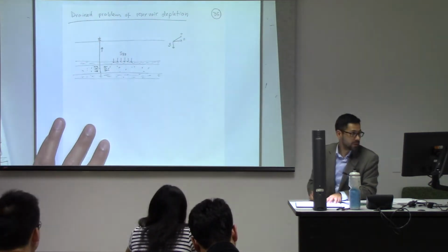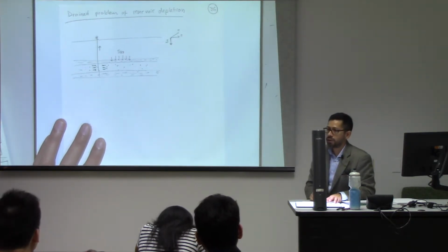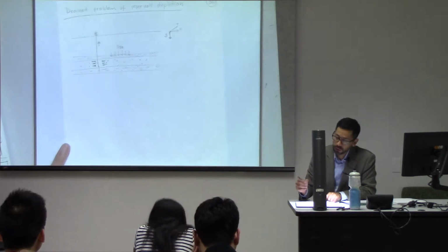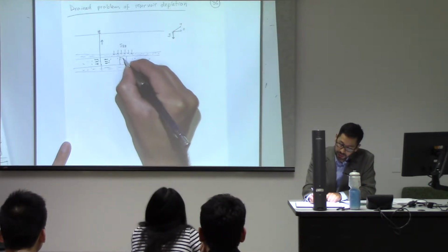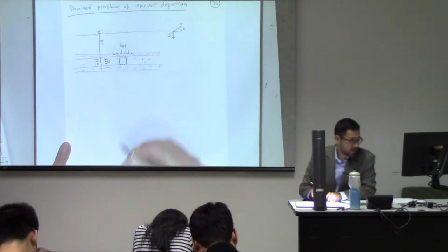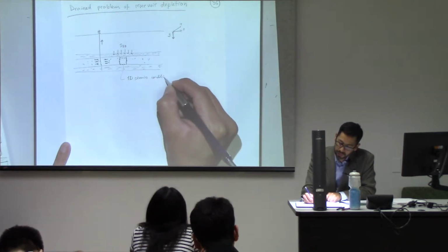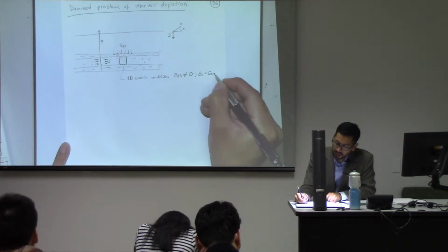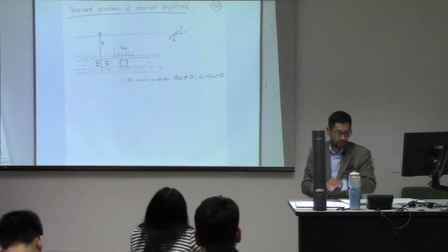I'm going to assume that the total stress overburden is going to be constant. And my objective is going to be to calculate the variation of horizontal stresses with decreasing pressure. Because of the geometry of the problem, I'm going to assume that after some time, the deformation of a section of the reservoir just happens in one direction, something that we have called the one-dimensional strain condition. And for this 1D strain condition, the vertical strain is going to be different than 0, but the horizontal strains are going to be 0. There is not going to be any change as we apply depletion.